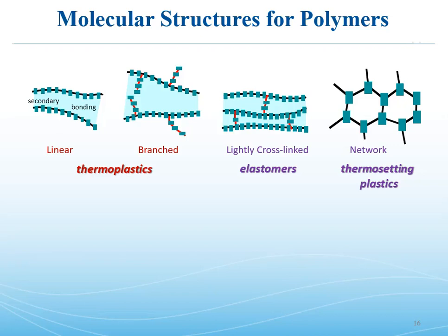And again, we had gone over how polyethylene can be linear or branched, and if you think about the opportunities, say, in a polar polymer that might be branched, you can't get those polar groups in close together where they can associate if you have branches in between. You can think of the branches as being an extreme case of steric hindrance, like that big bulky phenyl ring in the case of polystyrene.